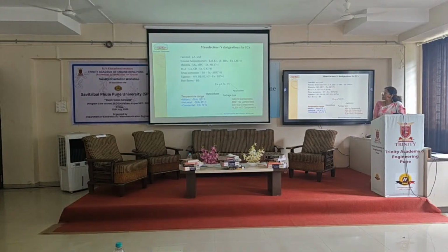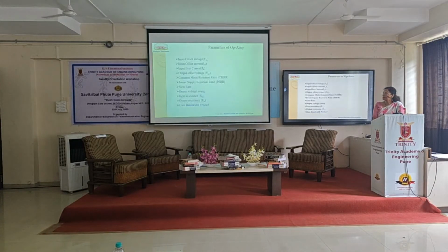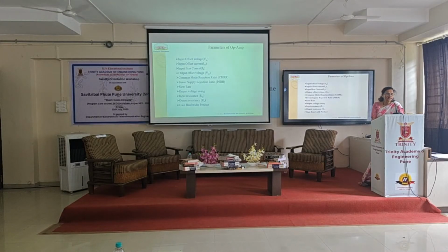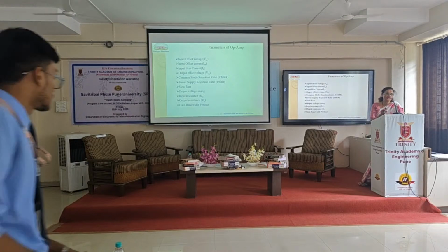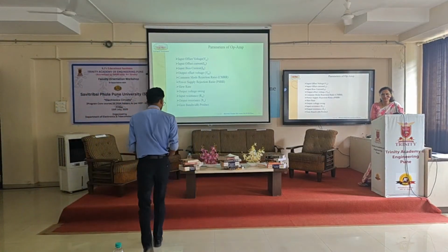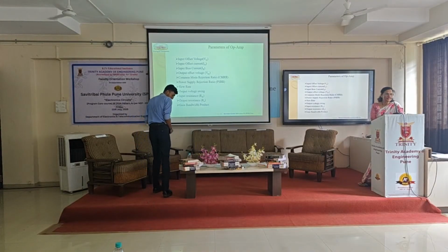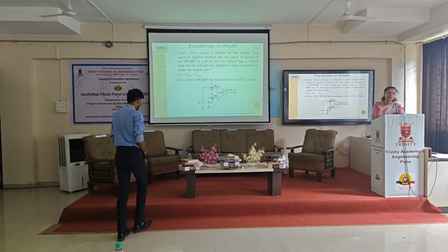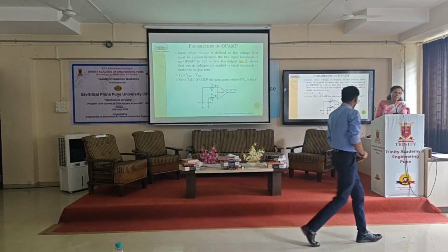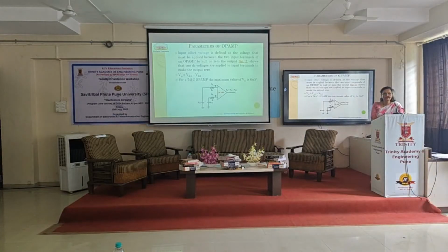Now, different ICs you have mentioned here. Now, after that, various evaluation parameters. Okay, we have to discuss one by one, along with its standard values related to a particular IC, for example, for 741 and for the LM series. While discussing these performance evaluation parameters, it is very essential to give more stress on slew rate and CMRR.